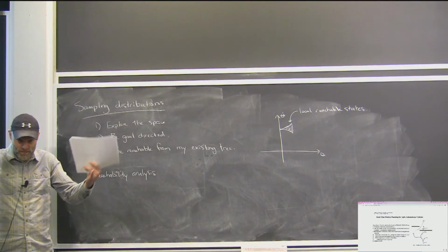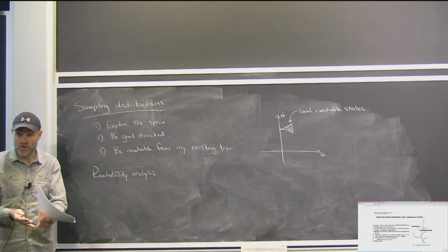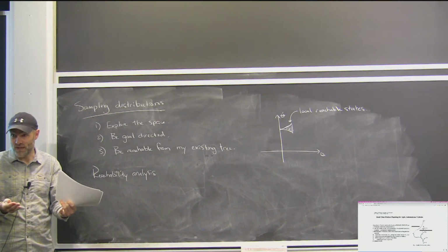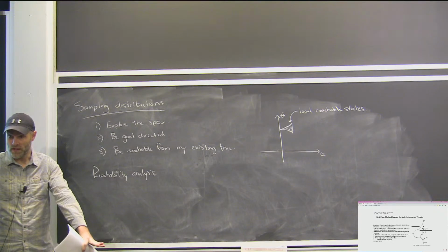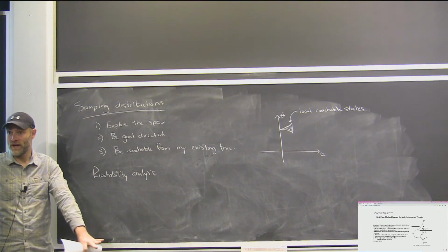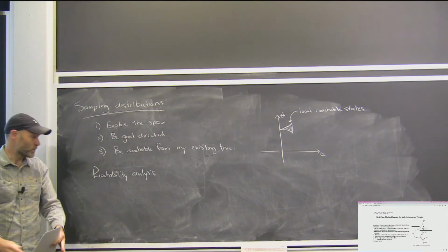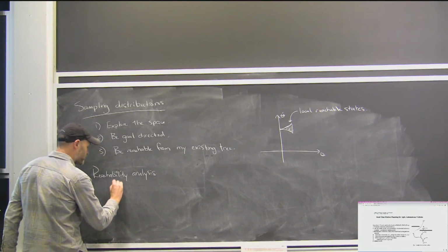The Lyapunov function tells me all the states that can potentially converge to a goal, for instance. Reachability analysis, you can use the same Lyapunov-like functions to talk about, from a point, where am I going to be able to get to in some finite amount of time. They're very closely connected to Lyapunov functions.